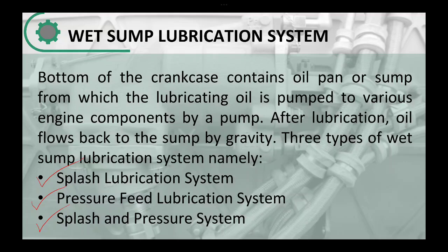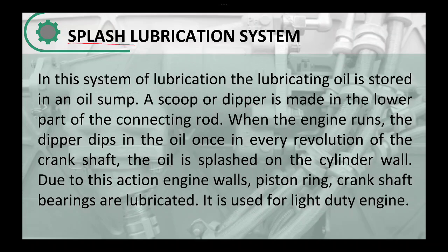Okay, let me start with the wet sump, specifically splash lubrication. So when you say splash, there's a sump of oil that will be scooped or dipped. Okay, so in a splash lubrication system, you do have this scoop or dipper, and that would wet the system. Okay, the scoop will scoop lubricant, then splash it to your system. Okay, this is how it works.